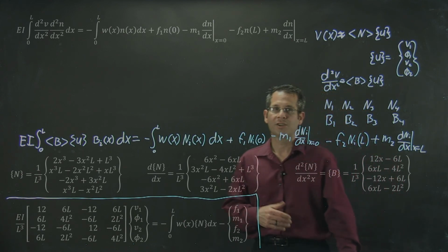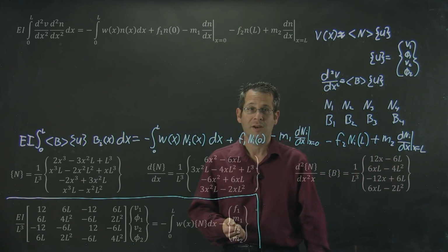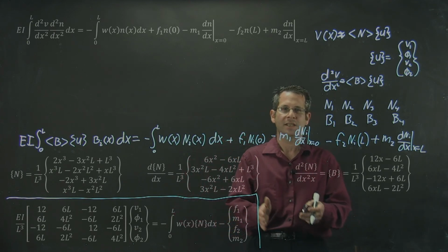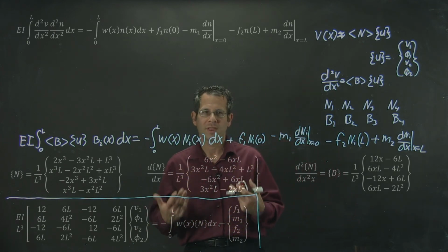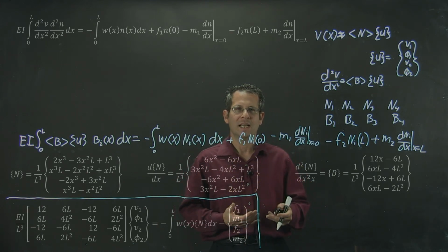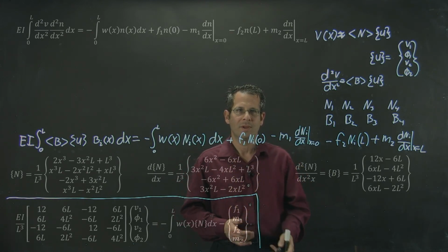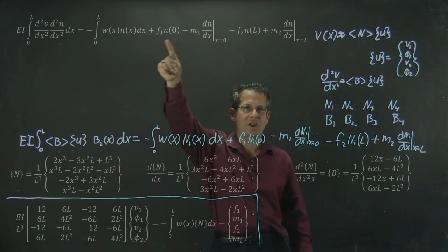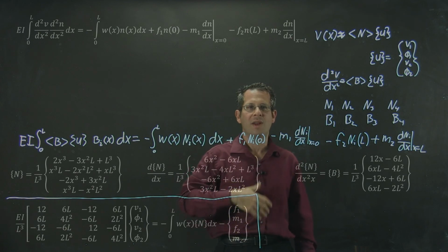The reason to derive the principle of minimum potential energy method is just because it was a way of getting to this form back when we were thinking in terms of having to have some understanding about the physics behind our problem. Galerkin's method allows us to just have knowledge of our differential equation. I don't have to think about the physics.